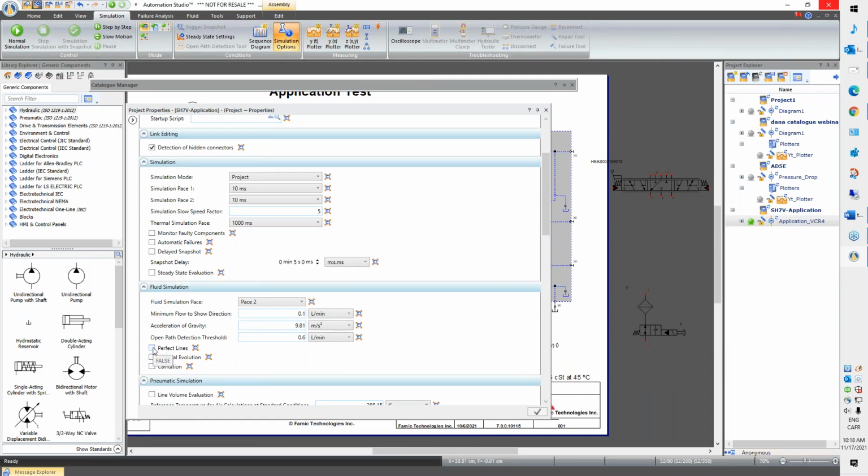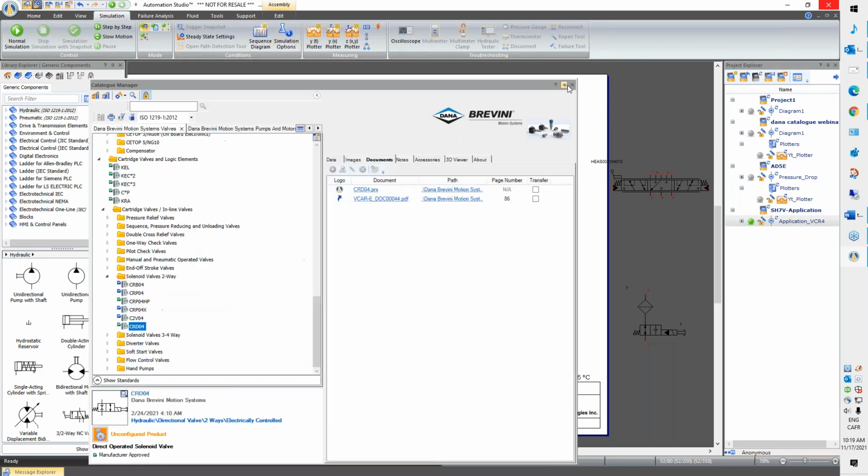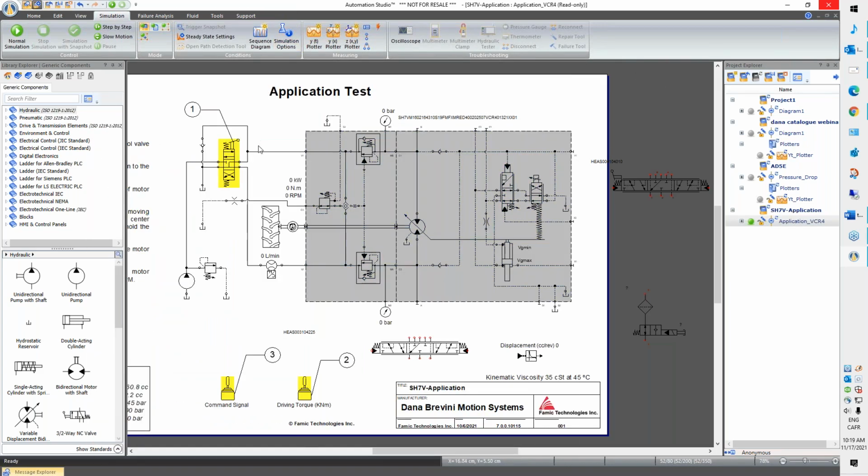At that point, you will not have pressure drops across any line. So if I select that, I can say the lines inside the motor, I will disregard those pressure drops and those volumes, and I will only simulate everything that is outside.